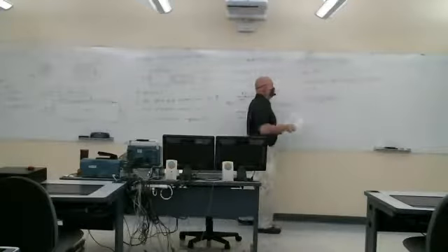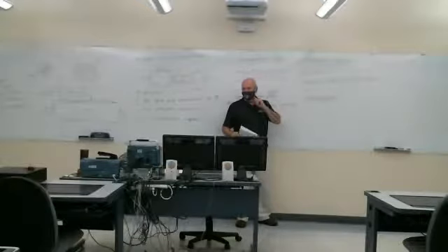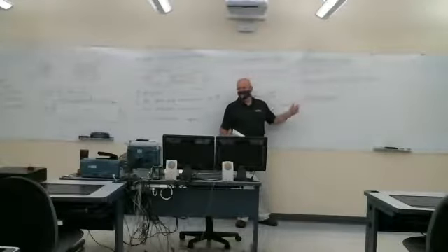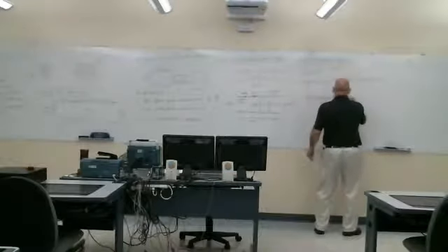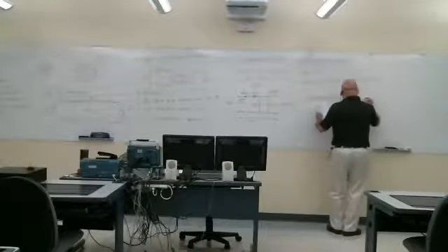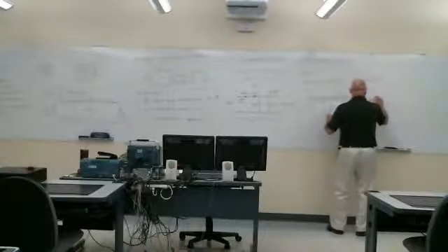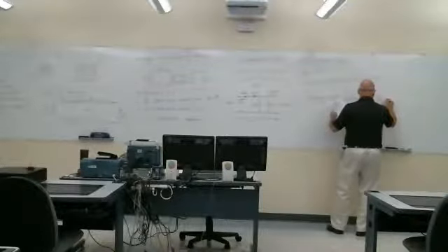So this is what I get when I move the voltages to the other side of the equal sign, right? A minus in front of that difference. And then that's going to be equal to R prime I(z, t) plus L prime, the partial derivative with respect to t of I(z, t).